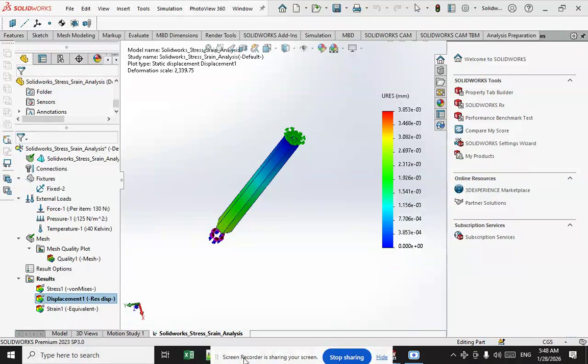Stress analysis can be performed experimentally by applying forces to a test element or structure and determining the resulting stress using sensors. In this case, the process would more properly be known as testing. Destructive or non-destructive experimental methods may be used in cases where mathematical approaches are cumbersome or inaccurate. Special equipment appropriate to the experimental method is used to apply the static or dynamic loading. There are a number of experimental methods that may be used.